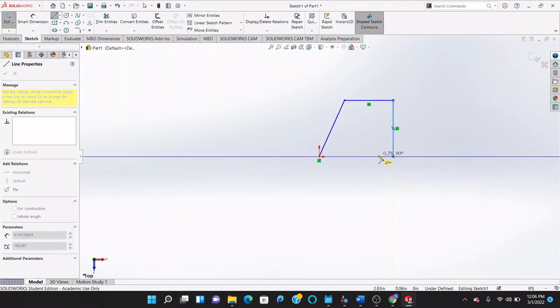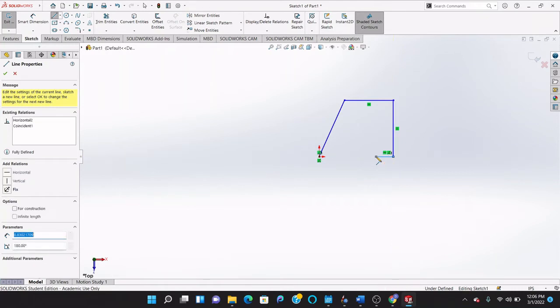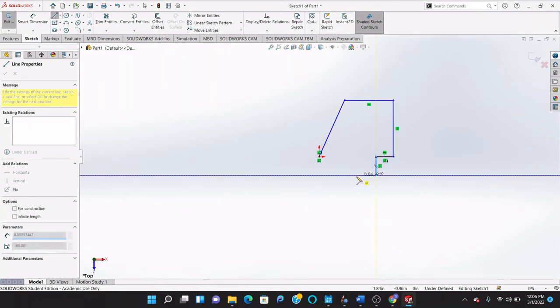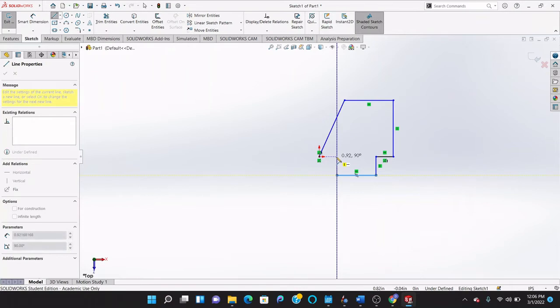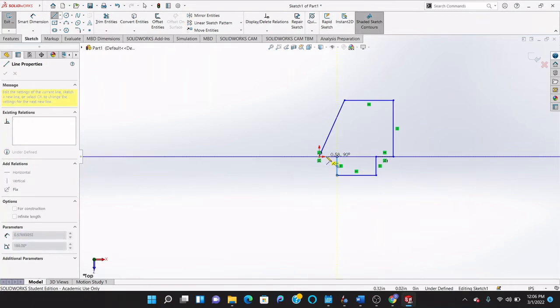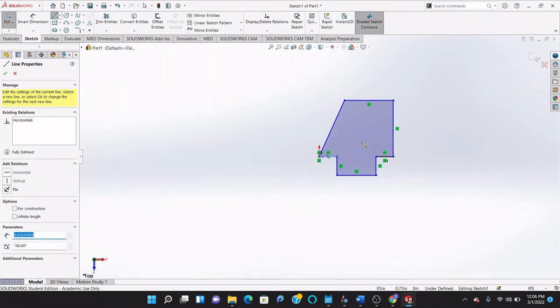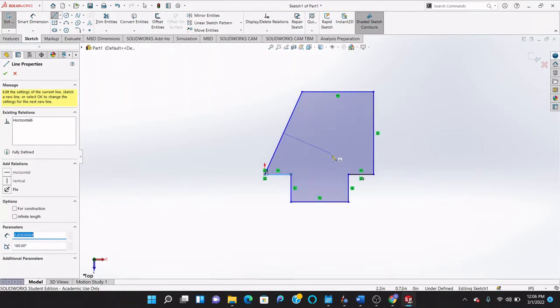All right, so now I'm going to move it to this point and click again, again, again, and then make sure you click on the same point you started at to close off the shape. And you'll see something happen when I click this last one. The shape turns a different color. It's now gray. Gray means it's a closed contour. It's a closed shape, which is good. You need a closed shape to be able to use the next feature I'm going to get into properly.